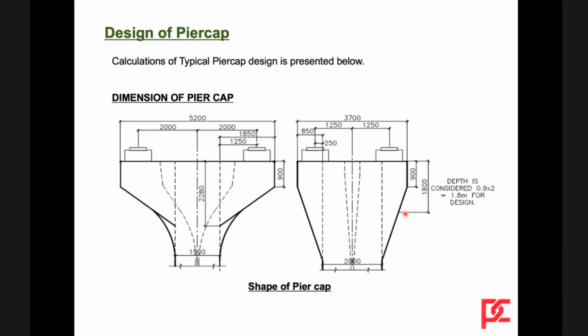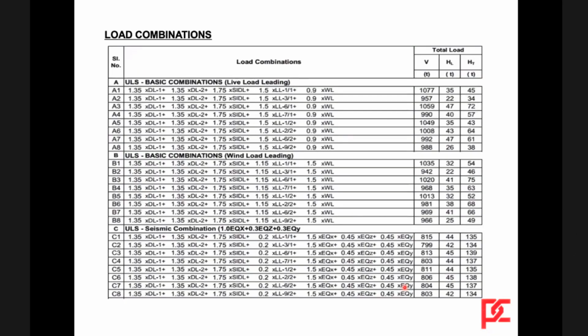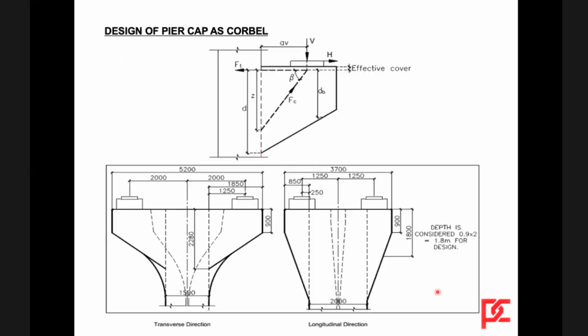And these are the typical loads that come from the bearings. They're all listed here. And for the various load combinations, what we have done is shown here. And similarly, for different combinations, a lot of computations are required. And finally, at the end of the day, these are the design forces we have arrived at. And this is a typical design.